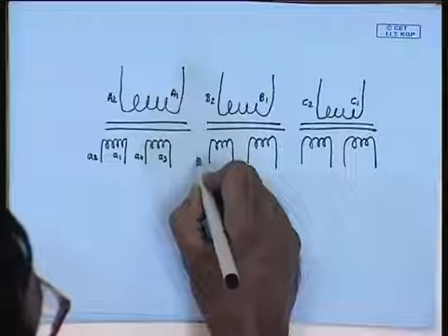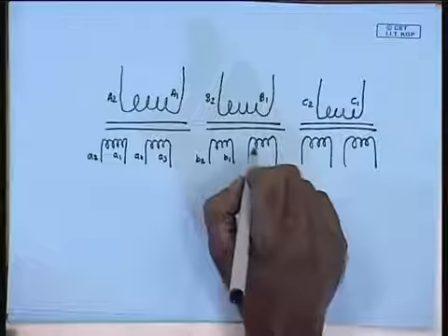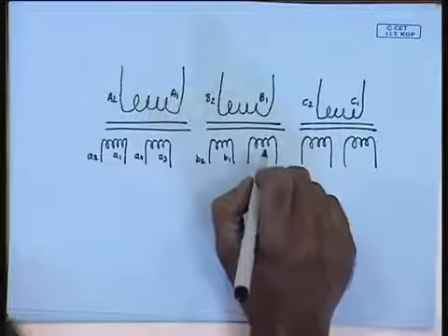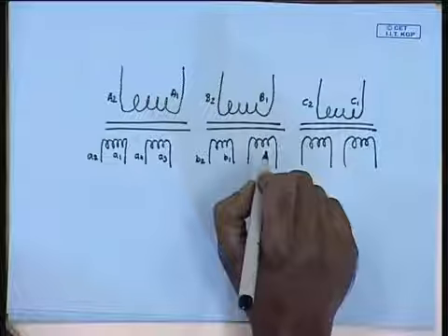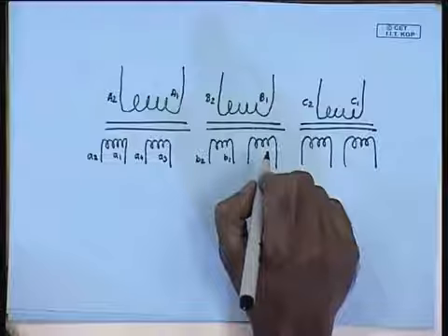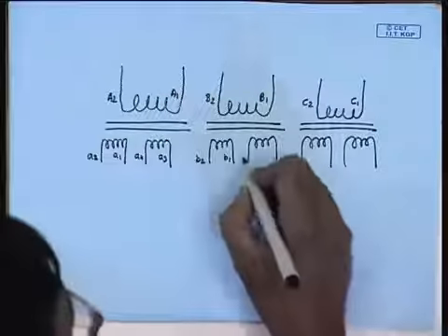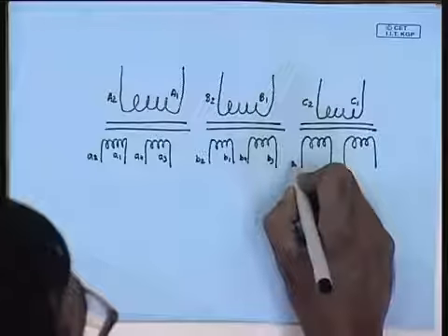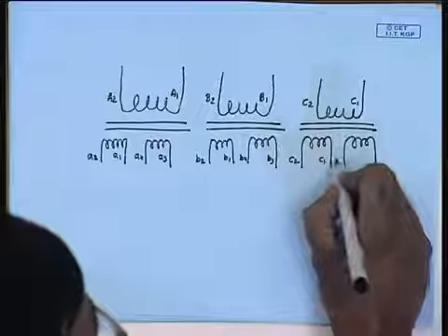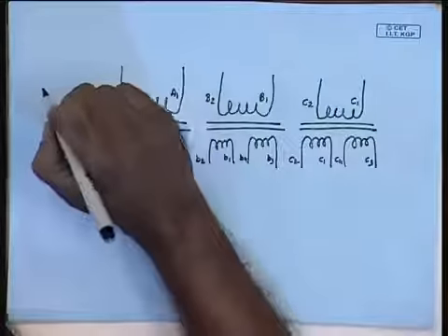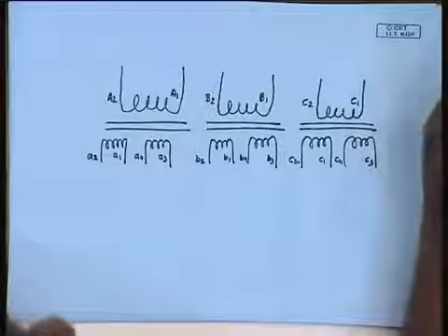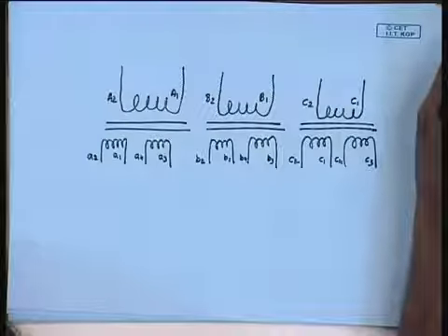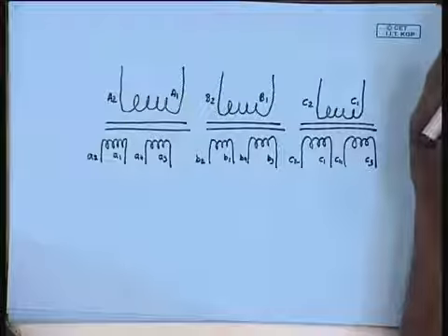This is B2, B1, this is B4, B3, this is C2, C1, this is C4, C3, indicating all the even numbered terminals have the same instantaneous polarity and all the odd numbered terminals have the same instantaneous polarity.